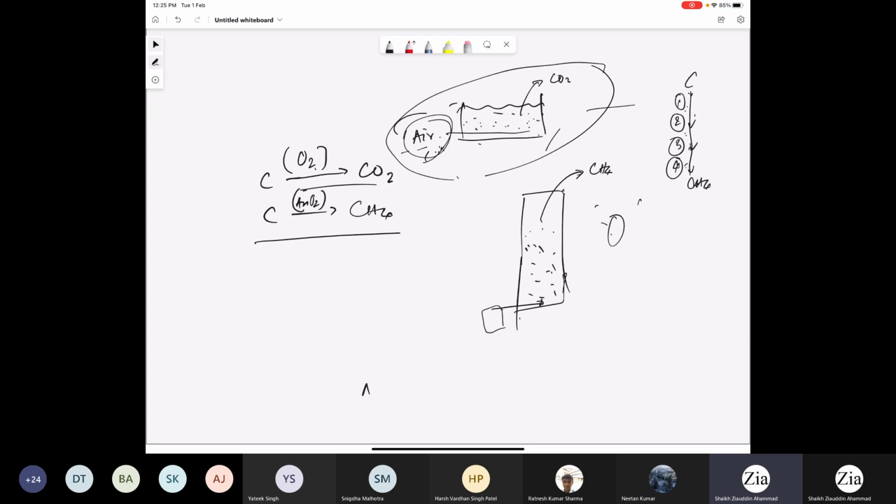So if you have higher carbon content, it is more favorable for this kind of reactor. That's why when you have a high concentration of carbon in the wastewater, you prefer to use an anaerobic reactor system. Although you have to use a little bigger reactor volume, you still prefer it because the amount of methane you can obtain gives you a lot of revenue, as you can get a lot of energy by burning or converting this methane.